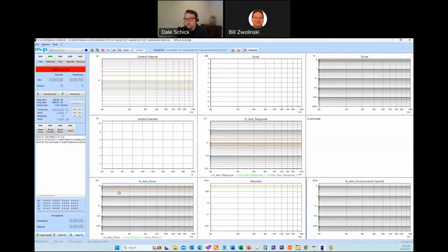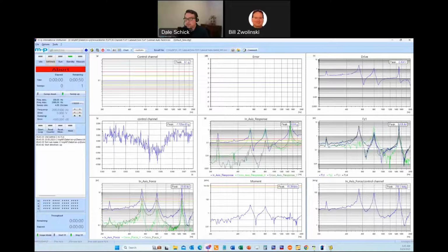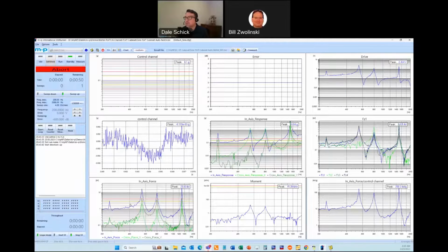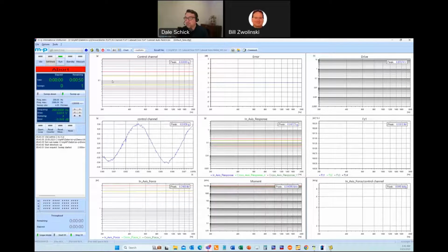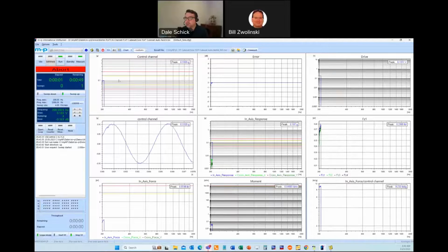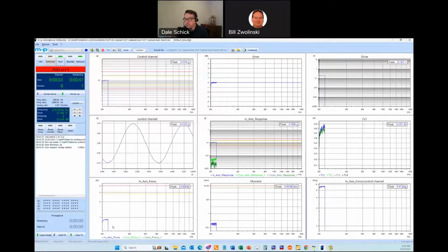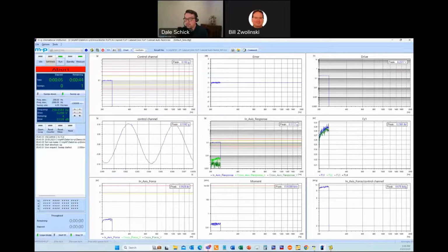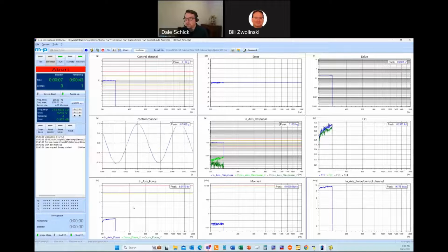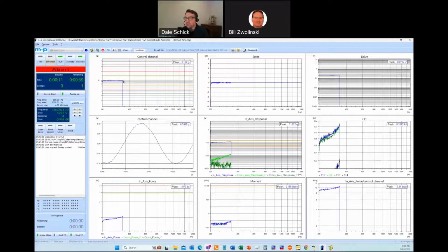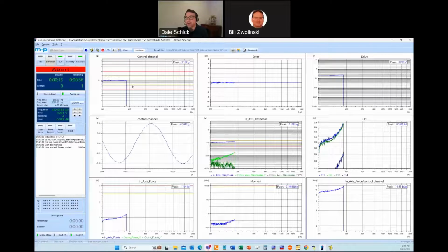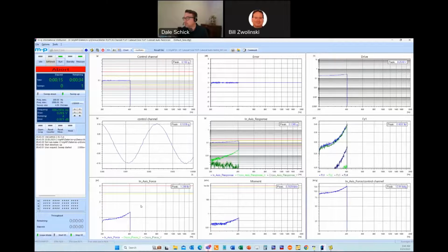And on this one, you're going to see the in-axis force actually has a notch drawn across at 2 pounds force. So as I begin to run, you can see our profile is built flat. We have 0.1 G all the way across. And what I was expecting to see is that as this in-axis force approaches 2 pounds, this notch should kick in and relinquish control from the control accelerometer over to the in-axis force.